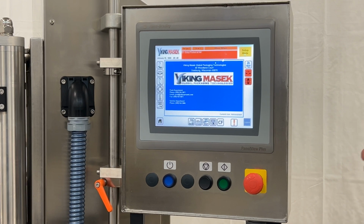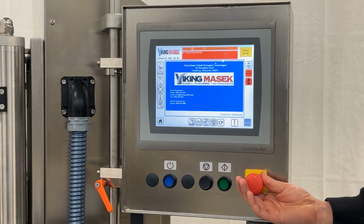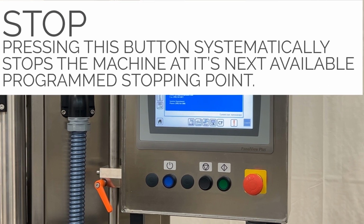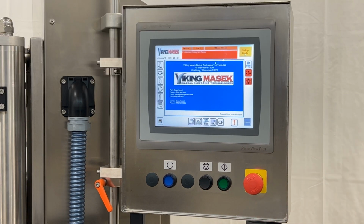After pressing the emergency stop button, it remains engaged. Pull out and rotate the button for disengagement. Stop. Press this button to stop the machine. Pressing the button systematically stops the machine at its next available programmed stopping point.